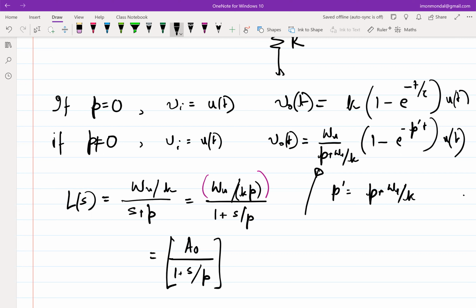Right. So now omega u by s, that is in Laplace domain. In time domain, what does it mean? Yeah. So it's an ideal integrator, right? So you're integrating sine. So in other words, you will essentially get whatever input was there. So you will get the gain of the integrator, that is omega u, and you have integrated it, which means omega naught will come out: sine omega naught t minus pi by 2. That minus pi by 2 comes because you have additional phase of pi by 2. So it's basically nothing but you take sine and integrate because it has gone through an integrator. It's a straight path. You don't get all these k terms because feedback is not working. Okay.